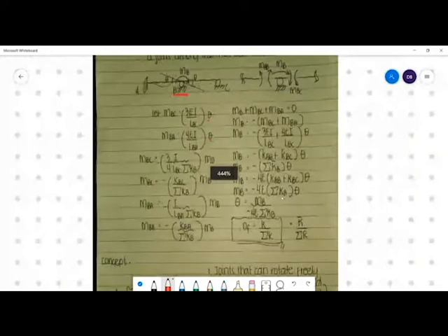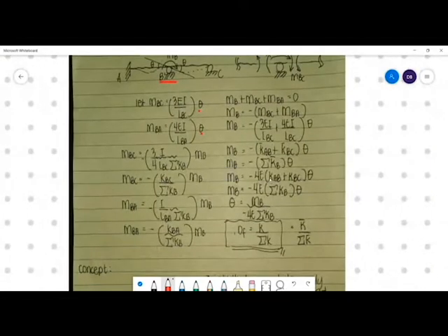When we take out the 4E, those are the absolute stiffnesses; once 4E is taken out, they become relative stiffnesses. Then M sub B is equal to negative 4E summation of KB theta, using the relative stiffnesses. So theta is equal to MB over 4E summation of KB.